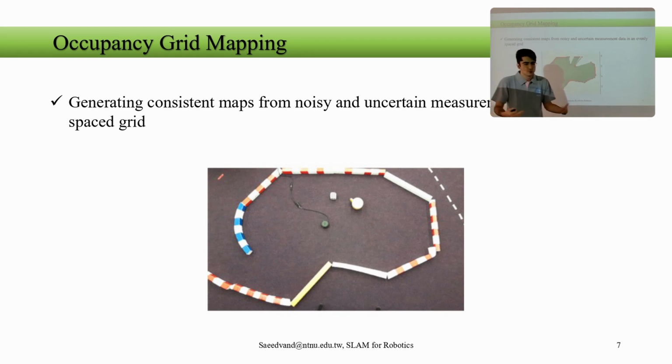If our robot moves, we can continuously do that by applying localization of the robot, and depending on how accurate we are, we can construct our map over each of the individual grid cells that we have. But what is the challenge? Why is today's course coming up? Because when your robot is moving with this sensor, of course we have error. And as I mentioned, we don't know how likely a cell is to be occupied, because multiple times we will see that it is occupied or not occupied, based on the error in our measurement model.